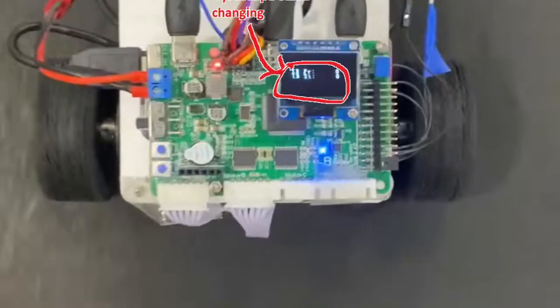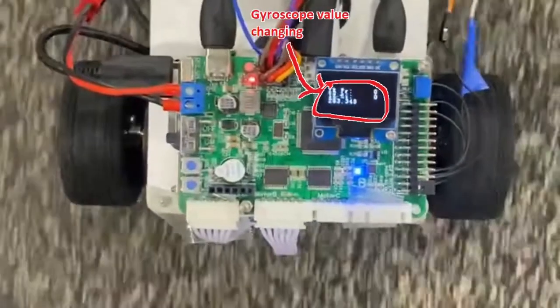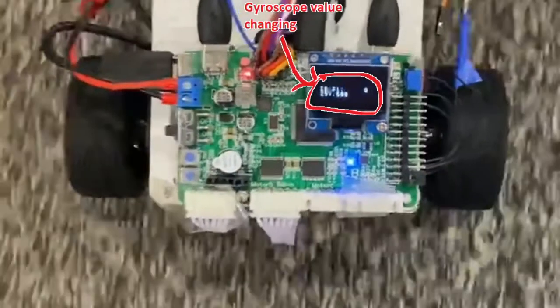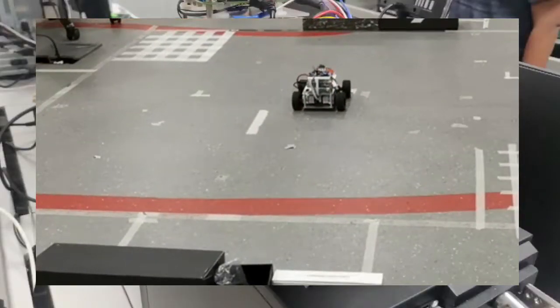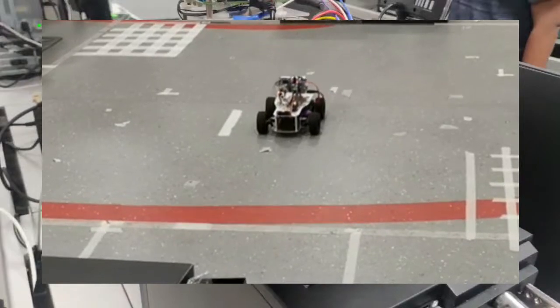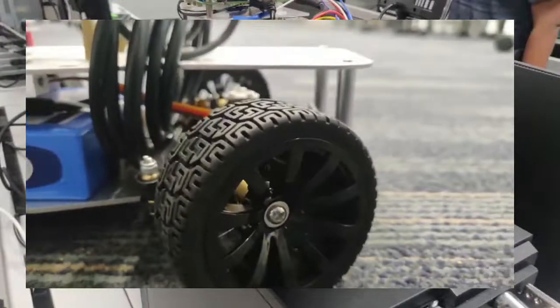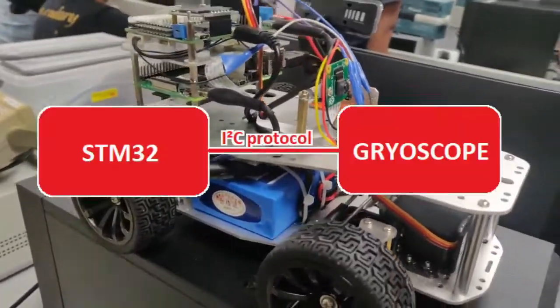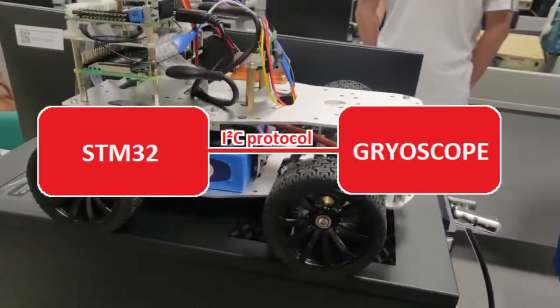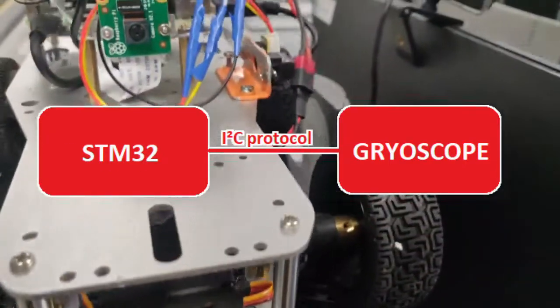And for that, we used the gyroscope present on the STM32 board in the ICM20948 IMU. Using the gyroscope, we corrected while going straight to align the robot to a perfectly straight line and while turning to make perfect 90-degree turns. The STM board communicates with the gyroscope through an I2C protocol.